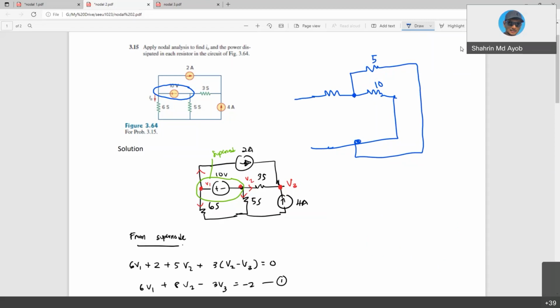And then maybe you have something like this. You have a 10 ohm resistor in parallel with a short circuit. Definitely, if you put it in parallel with a short circuit, your R is actually 0 here, because the current will flow through the short circuit. It will not pass the 10 ohm resistor, because the current will always flow through the branch that has the lowest resistance.